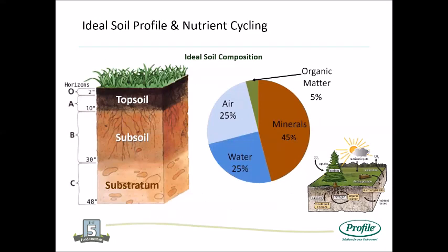All right, so what does a typical soil profile look like? Typically, we're most worried about our organic and A horizons. OA horizons are typically what we deem as topsoil, and those are really composed of about 45% mineral material, which most of our sites will have, and then about 50% airspace and water space, an even combination between the two. What's often missing on our sites is that 5% organic matter that really makes a topsoil a productive topsoil. It's everything, it's the lifeblood of your topsoil.